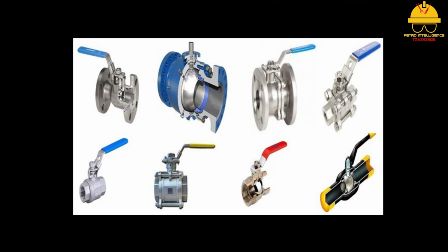Ball valves should not be used for throttling service. During prolonged exposure, the ball seats and ball can be damaged, stopping the valve from sealing properly. Typically, ball valves are not designed for excessive temperatures. The seats are made of a plastic-coated material that tends to break down under high temperatures. Process technicians should be familiar with the temperature specifications of the valves.